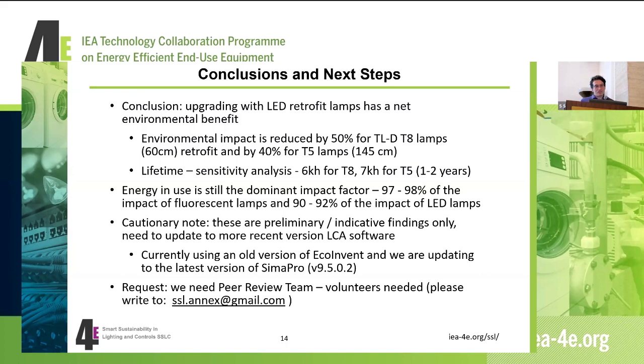For the T5, it's a little bit longer. You need about 7,000 hours. So pushing more 2 years for that. So if you're not going to change the fixtures within the next 2 years, definitely pop in an LED retrofit lamp. You will then have a net benefit overall from an environmental perspective. And of course, if it's going to be longer than that, if you're talking 3, 4, 5 years, it absolutely makes sense.